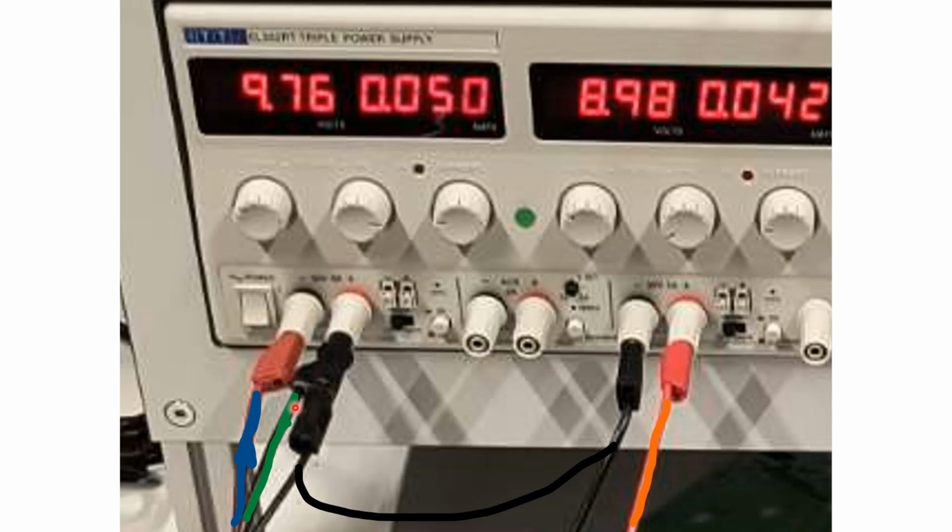And this green cable here is also at 0 volts coming from here. So that's going to go to ground on the circuit board. But then this blue cable here that I've labeled, this is 15 volts. Well, in this case, it's not, but on the actual circuit, it was 15 volts here. But this is 0. That means this must be minus 15 volts. So then that's where we got our minus 15 along this blue cable, which connects to the negative input for the op amp, for the negative power for the op amp.